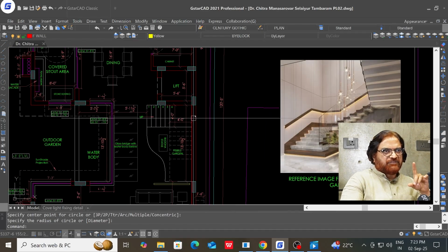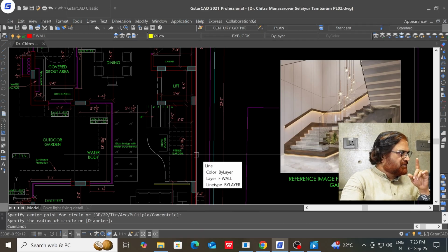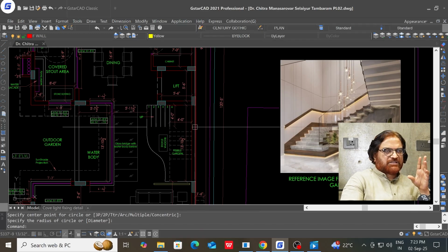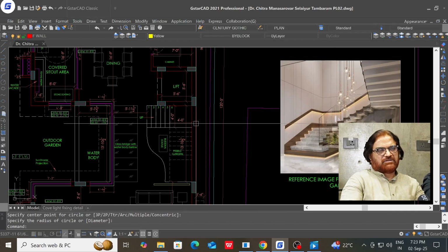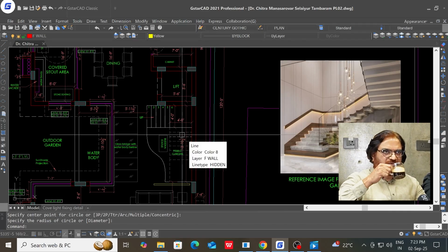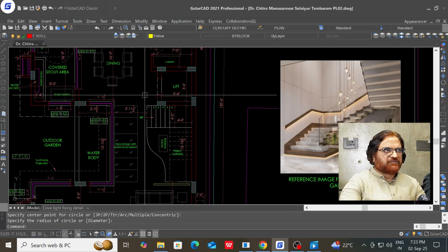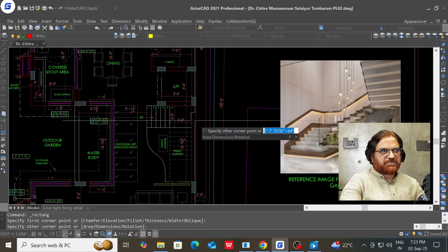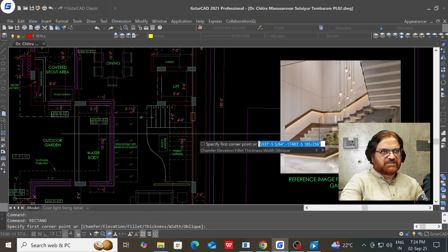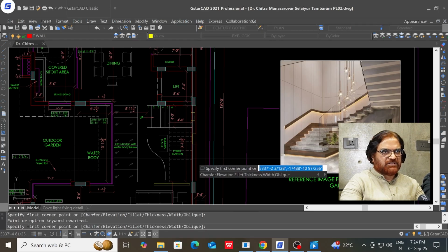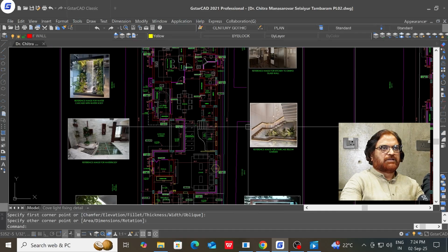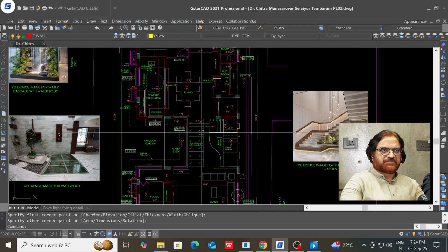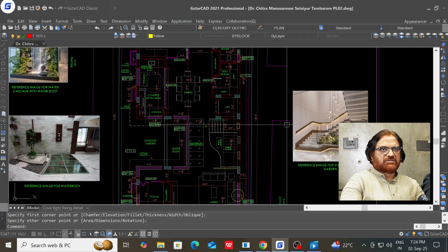And I think we have purposefully avoided windows here, isn't it? Are we going to have windows? It is better to avoid a window. If at all, you can have a very small window, because being the western side, it is going to receive a lot of sunlight. So I would like to have fewer openings on the western side. If at all you have slit windows, smaller size windows, which bring less heat inside the house. We always have to see the climatic factor, so that the air conditioning costing is not too much. So on this western side, we can have fewer windows, and wall treatment and all that we can see later.